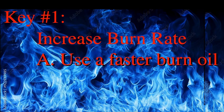A. Use the faster burn oil. I'm talking about engine oils, which many of the cool riders call premix. As you know from previous videos, synthetic is the slowest burning oil. It's also highly protective, but you really don't need it unless you have a high heat engine, which is indicated by your NGK spark plug number. If you're running a number 9 or number 10, yes, you need 100% synthetic. If you're using number 8 or number 7, you do not need a 100% synthetic.